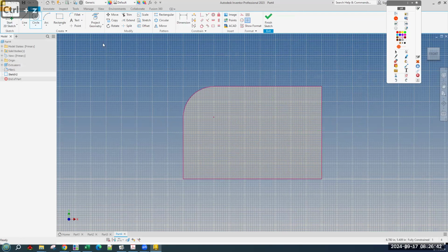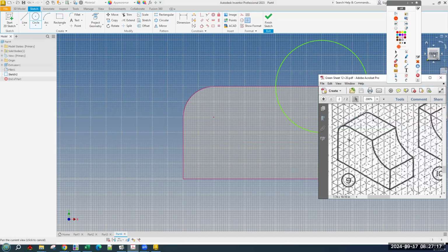The reason why we aren't doing an arc is arc gets kind of funky when you have different types. First of all, there's 3-point arc, which clearly we don't want here. The point is circles and rectangles are always closed loop. They're always constrained to their basic shape. And it just makes it easier when it's pretty simple. So we're going to get a circle and snap it to this top corner, the actual green dot, and make it about right. And let's see what our dimension is.